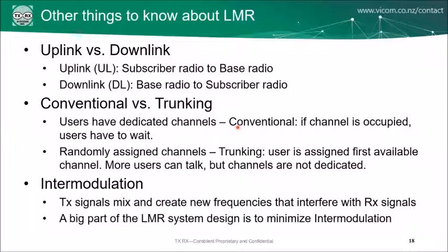We also have conventional versus trunking. In a conventional system, if you have dedicated channels and a channel is occupied, you've got to wait. In a trunking system, you have randomly assigned channels where the user is assigned the first available channel. In trunking systems, you can have more users talking at any given time, but the channels are not dedicated. There's advantages and disadvantages to both, which I'm sure somebody will ask a question on. Please do.